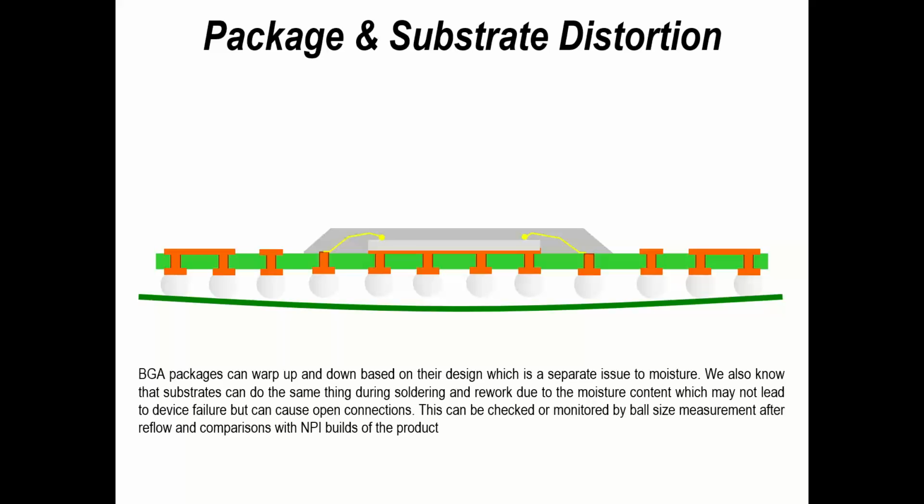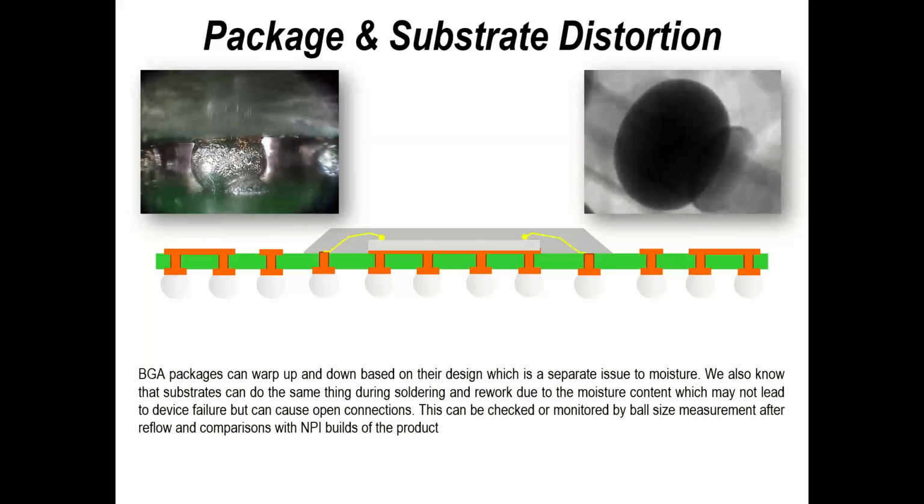And certainly I know a few Japanese manufacturers that bake their boards to make the boards more accurate for other operations. So it's nothing to do with delamination or damage. It's to do with accuracy of the assembly process, printing and placement.